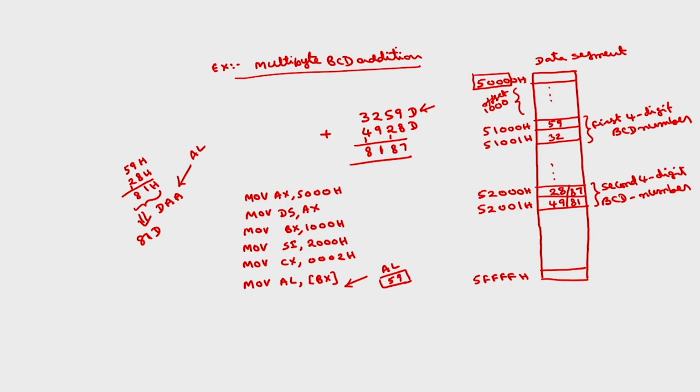Now we have to add to the previous one, ADD along with carry. Of course here there is no carry, carry is 0. After this addition you may get a carry from here to here. So for that you write an instruction to clear the carry, CLC, which we have discussed in the earlier class. This will clear the carry flag. So even if I use ADC here, because the carry flag was reset and none of these move instructions affect the carry flag, the carry flag is 0.